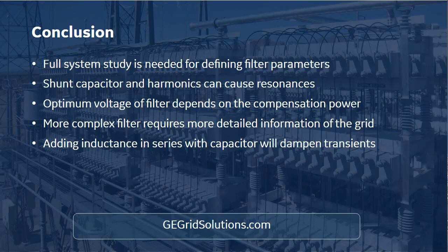And we have here one question, a specific question about a 33 kV system, where you have a requirement of compensation power of 20 to 35 megawatts in steps of 5 megawatts, and they are asking how it can be realized in open rack construction, multi-stage switching. The metal enclosed construction needs a substantially bigger civil footprint and it's not an economically viable option.